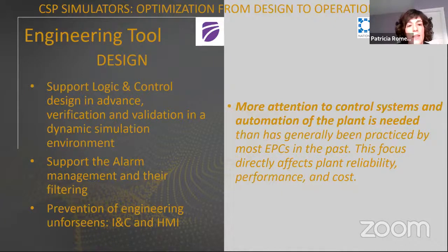In the design phase as well, NREL recommends that we pay more attention to the control systems and automation of the plants. As I said before, integrating the logic and control in advance in a simulator or in a simulated environment gives us a lot of advantages in order to detect logic and control mistakes, in order to remake them, and to check how to manage the alarms. That sometimes is not a good point.